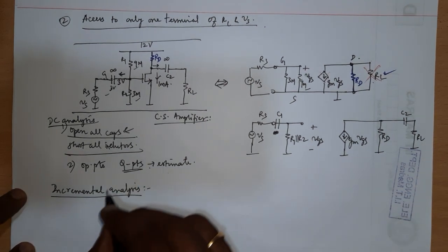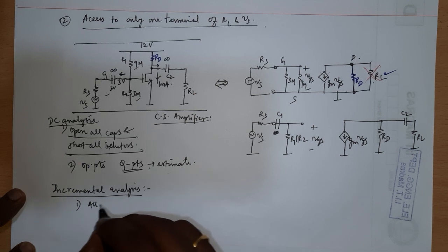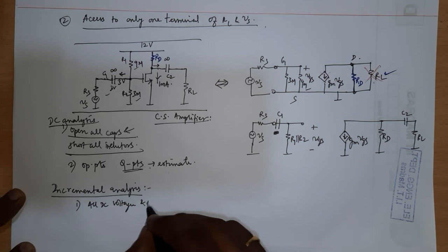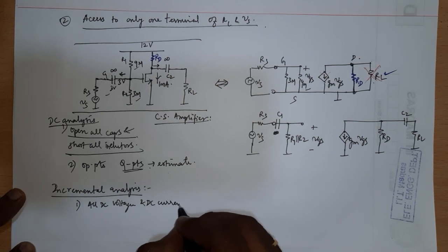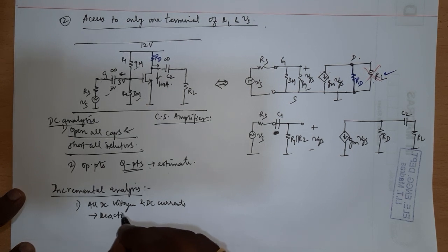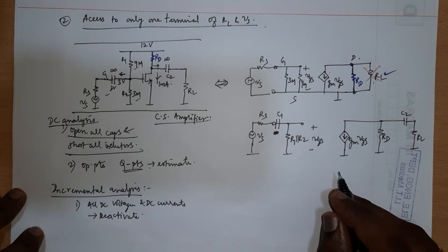So what you should do is, all DC voltages and DC currents you should deactivate, meaning all DC voltages should be shorted, all DC currents should be open.